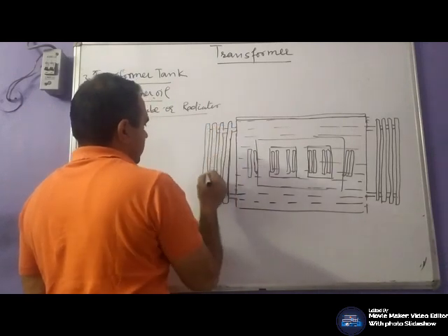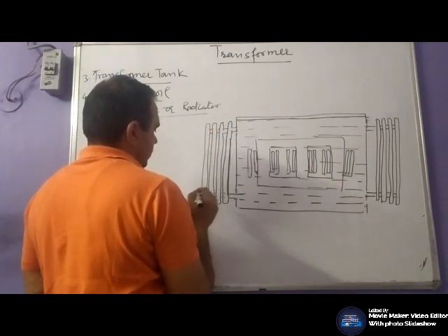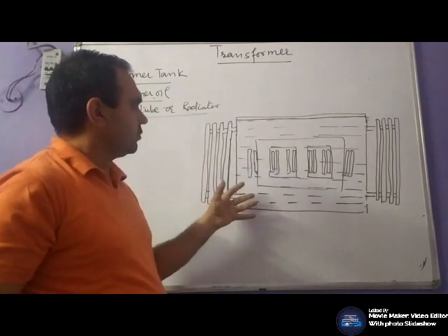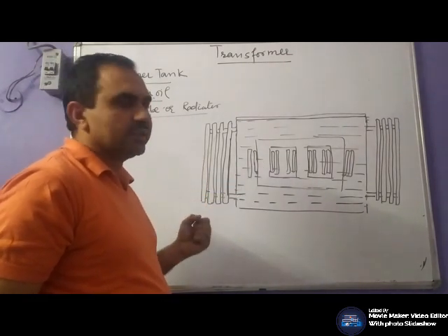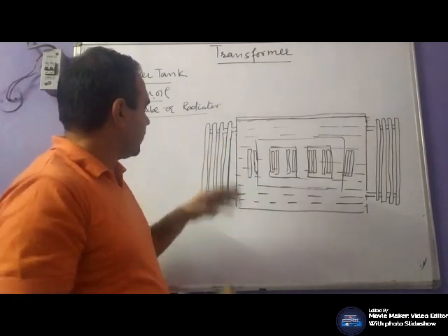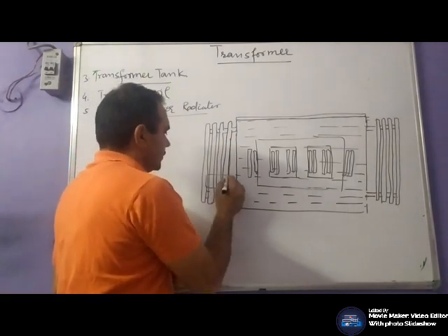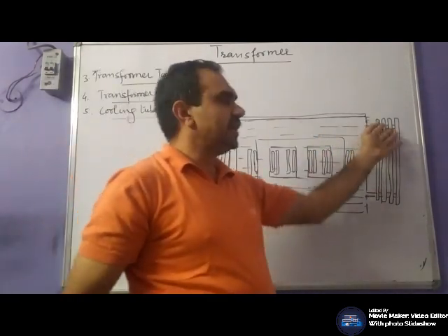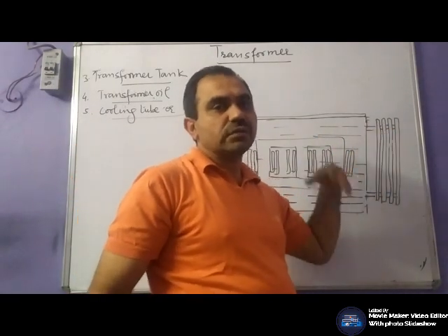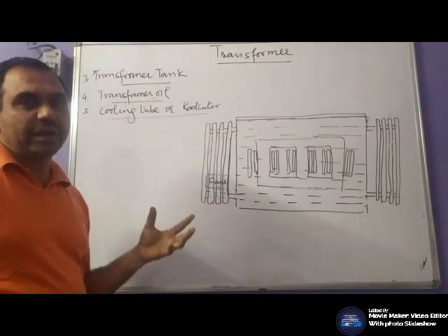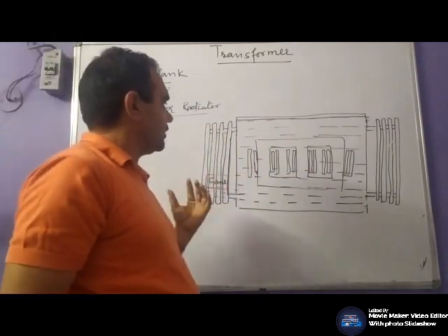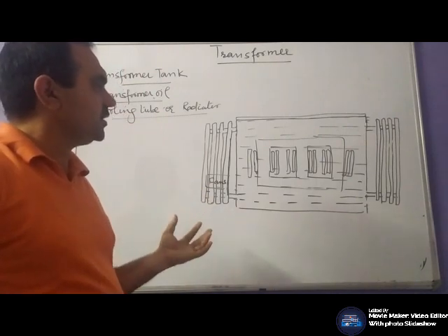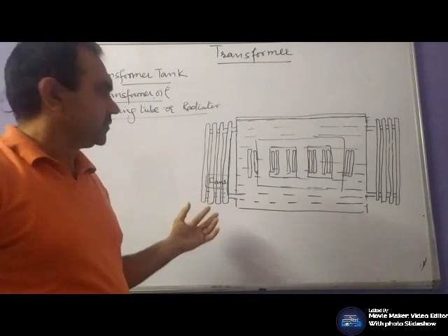To cool down further, so that heat is extracted faster, you can place fans on the radiators. Fans are placed on the radiators so that they provide better heat extraction, and heat is extracted at a better rate.